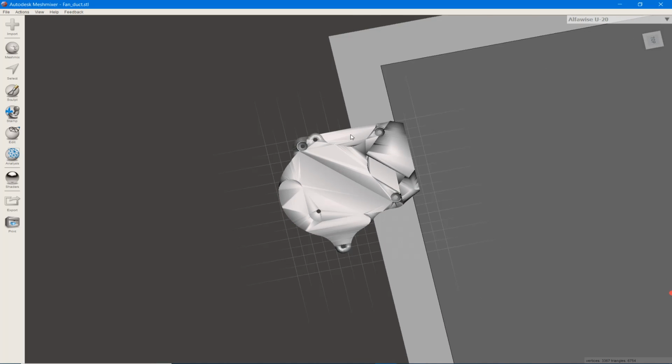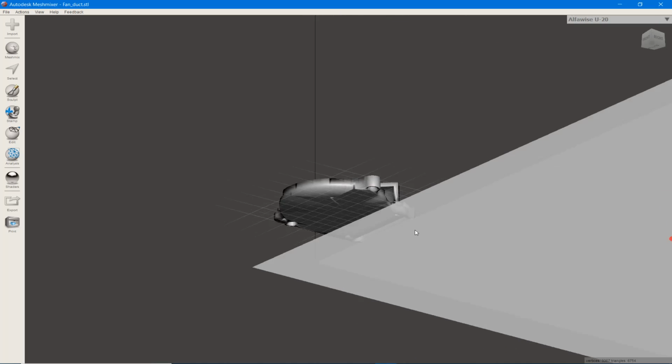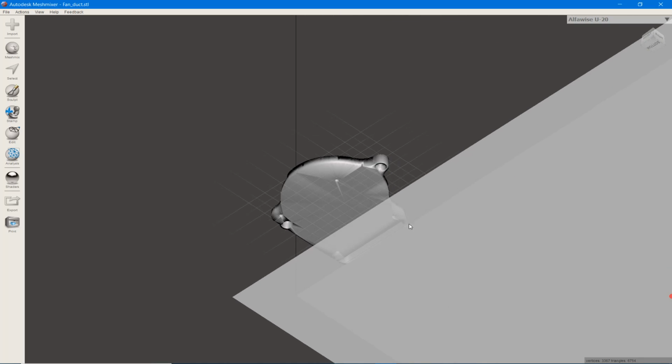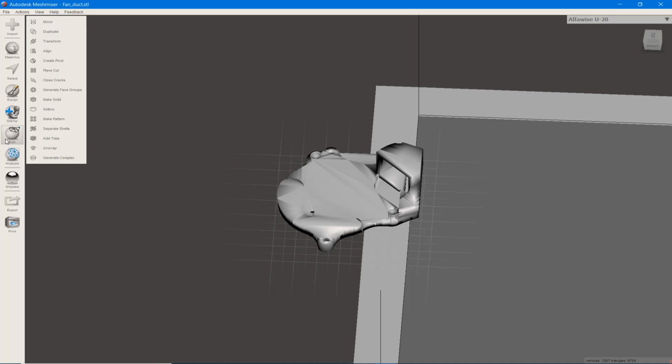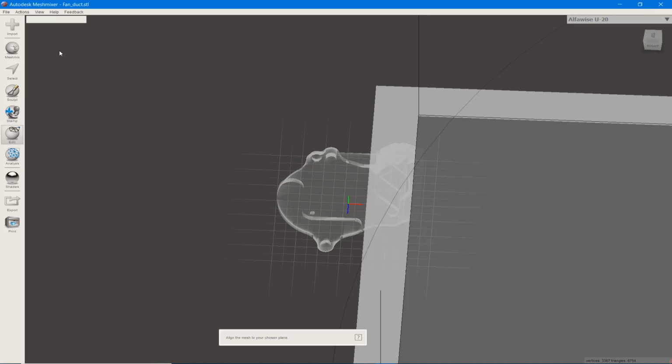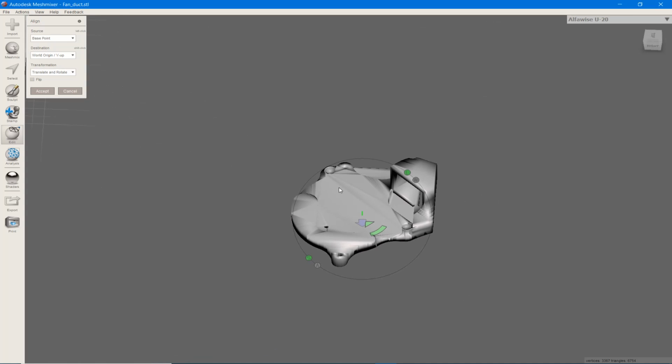These 4 holes here, here, here, and here, they mount to the stock Ender 3 sheet metal hot end cover, and then these 2 holes here and here mount the blower. The blower blows into there, and you can't see it really well, but then it blows out there in pretty much the same position the stock part cooling fan blows out of. Let's get this thing into the middle just to make it easier for us. So we're going to go up here to edit and align, and there it is.